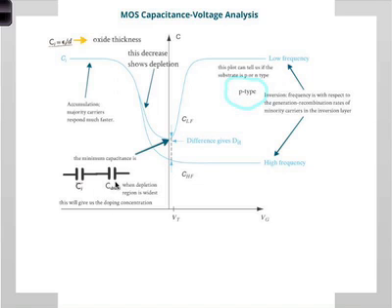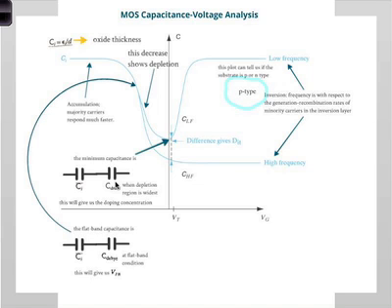And by knowing that, we know the maximum depletion width. As we'll see shortly, from the maximum depletion width, we can extract what the substrate doping is, which is, again, an important parameter, difficult to measure typically. Okay? Now, we'll go back and talk about it in a second. But around here somewhere, flat band condition happens.